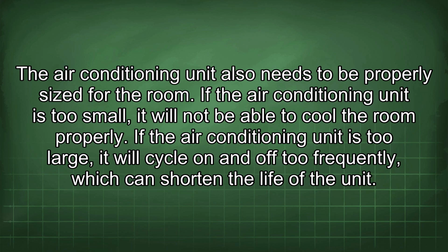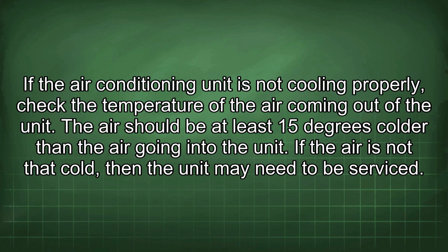life of the unit. If the air conditioning unit is not cooling properly, check the temperature of the air coming out of the unit. The air should be at least 15 degrees colder than the air going into the unit. If the air is not that cold, then the unit may need to be serviced.